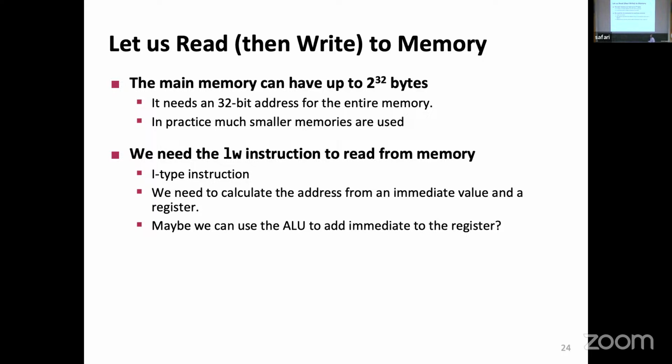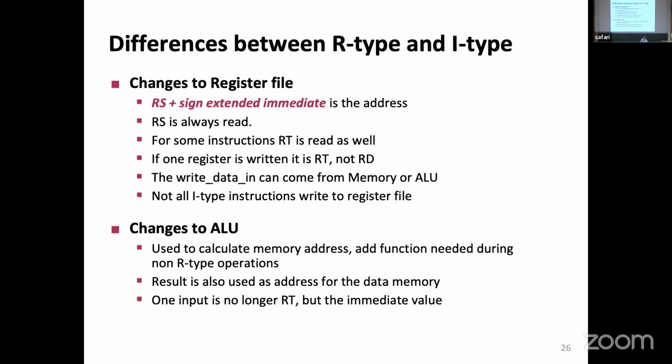So you say, where's the constant? Well, the constant is encoded in the instruction, the first 16 bits of it. I can take this constant and expand it and add it to the register. I can reuse this ALU and tell it, take the register, take the constant, add them together, and then we have a result. So this is what we were doing.